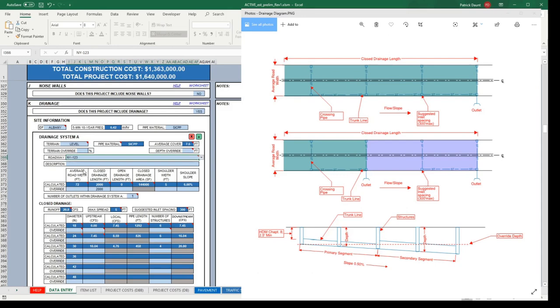Now if I go ahead and change to Main Street, which I know is not a freeway, you'll see that we've gained 2.5 feet of allowable puddle spread, because we can now go half a lane into the travel lane for your puddle. That's great. Let's just go change this back.